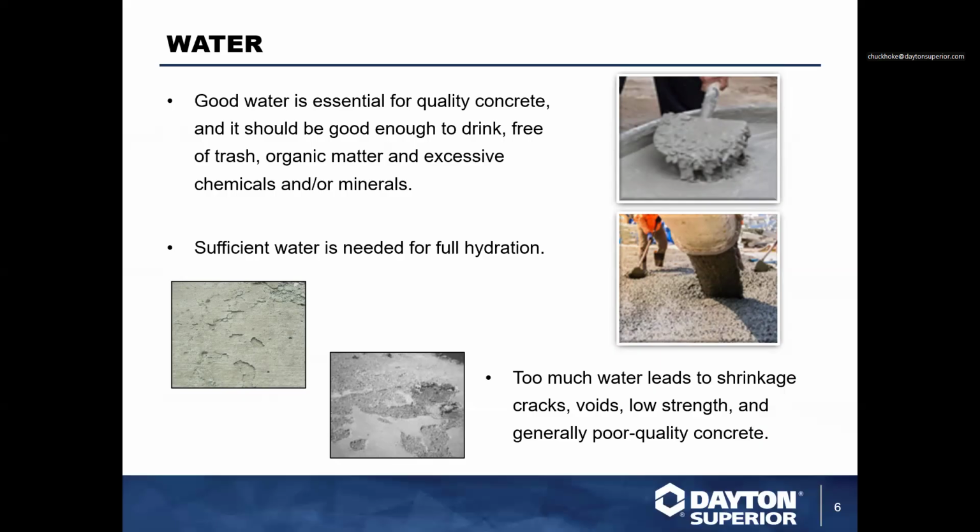Now, when I say sufficient hydration, we don't want to get it too wet, because the wetter you make your mix, the weaker the concrete is. So you kind of thin it out. Basically, there is a point where you can go to where it's just right, or you can go just a little over and there'll be a little bit less strength. But if you go past that component, you will actually cause the concrete to lose strength. You'll end up increasing shrinkage cracks, voids, low strength, and generally poor quality concrete.